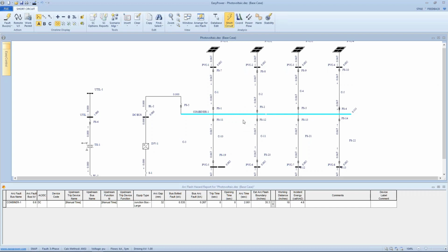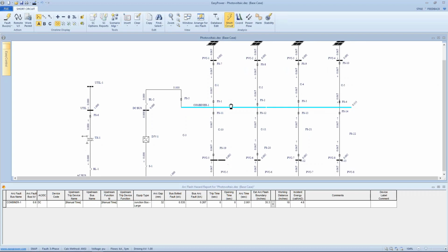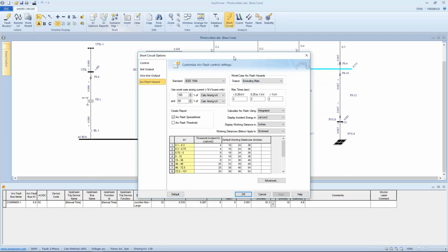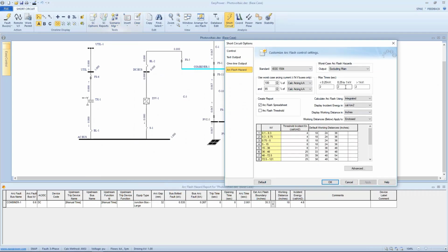at a steady state rate. Now, the point I want to make with all this is that the problem with using this short circuit voltage setting is this applies to a voltage range, not just certain components. And so if we have a 480 volt system over here or a 600 volt system, AC system, this limitation is applying to them as well. And I don't think that's necessarily a good idea if we haven't looked at the currents involved.